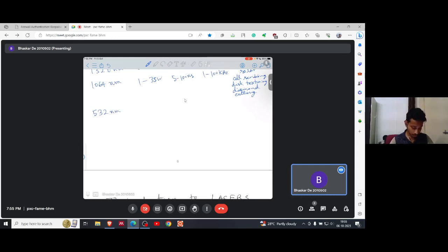532 nanometer, which is 0.5 to 20 watt power, 5 to 70 nanosecond, 1 to 50 kilohertz. Applications: marking, PCB structuring, drilling, cutting.